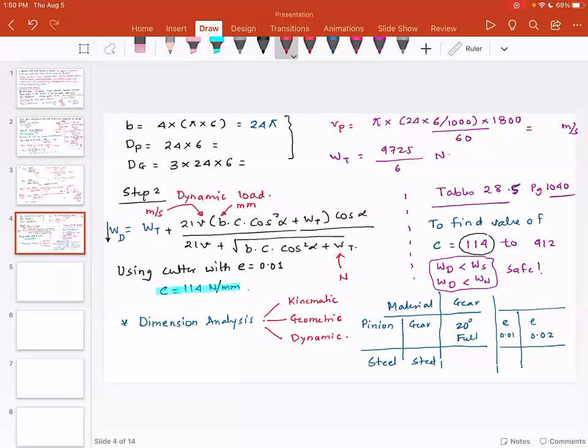A word of caution: the kinematic similarity may be 1:10, geometric similarity may be 1:5, and dynamic similarity would be 1:1000. So you have scale issues, but the dimensional analysis would take into account these differential scalings and still give you a consistent result. And that is where this equation is coming from. The reason for that is you have different units on velocity, which is in meters per second, and the length unit is in millimeters. So something to keep in mind.